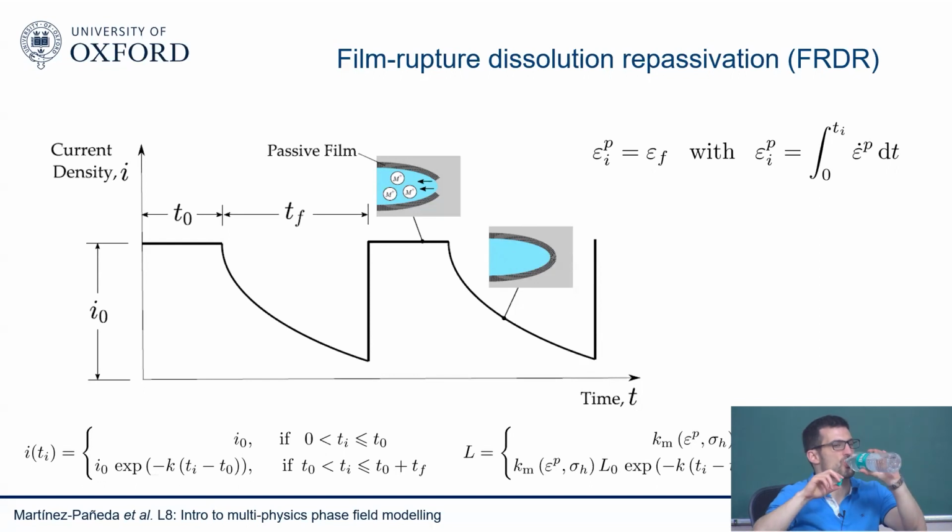Emilio, do we account for the thickness of the film that ruptures, or is it not really required? Yeah, because it's so small, I think there have been people doing some interesting experiments, and they seem to be able to predict that the failure strain, which I think they saw was 0.003, will always be more or less the same number, even if they weighted a bit more and stabilized it a bit more. So it seems that maybe because it's so thin, it doesn't matter that much, and just considering that failure strain will be enough. I mean, it's an approximation. I think it's a sensible one, but of course it's not for sure what happens in reality. So this is a critical aspect.